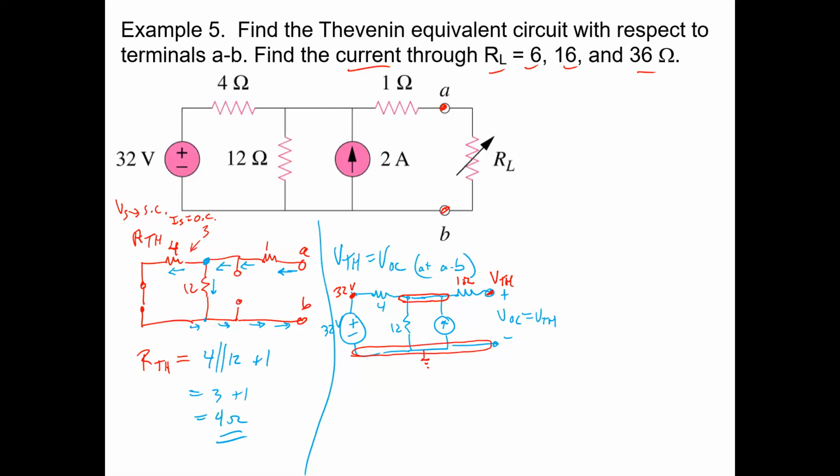Good. So if I equals 0, what's the voltage drop across the 1 ohm resistor? 0, right? So this is an example of what you would call a dangling resistor, which has no voltage drop. I'm calling this a dangling resistor because it's dangling in space, right?